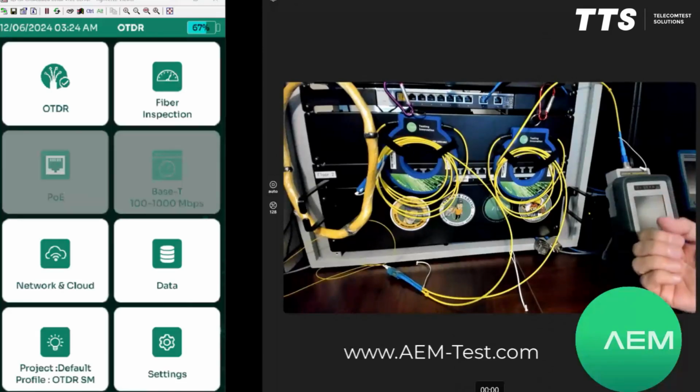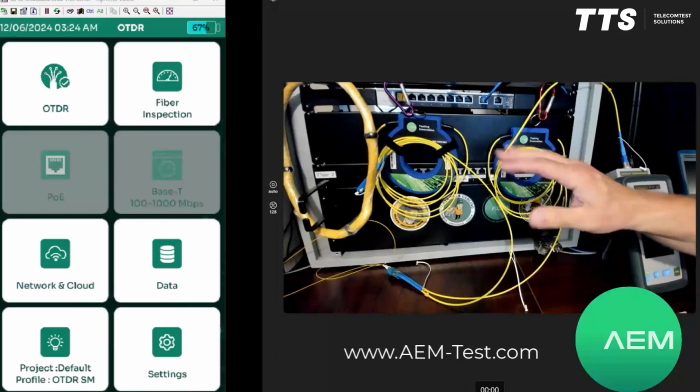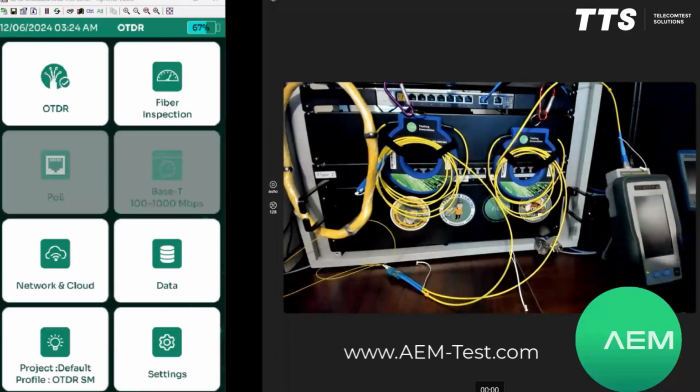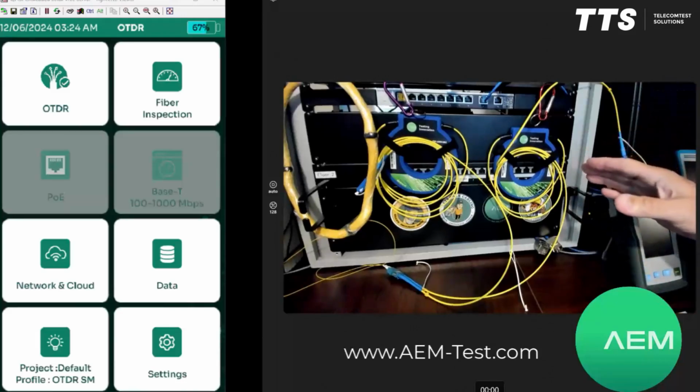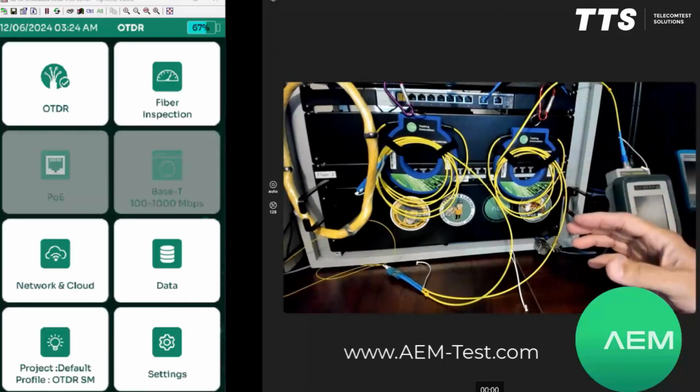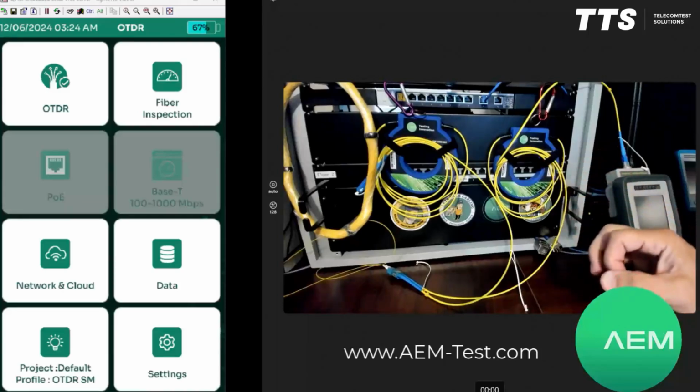And then the tail cord provides a reflection point at the far end for the far end connector of that fiber under test. So I've got a launch cord here and a tail cord. They're both the same cord. They're both a launch cord. My OTDR has an SC. That's what we ship this with, an SC connector on it. The cord that we typically recommend and that I'm using here is an SC to LC launch cord. I've got two of those. These are 150 meters in length.